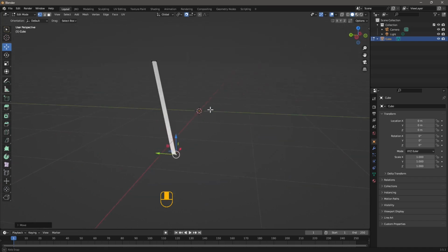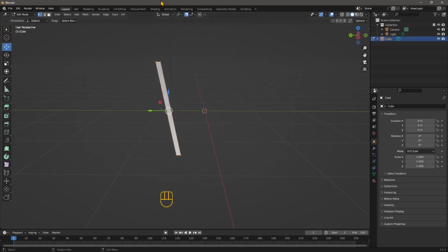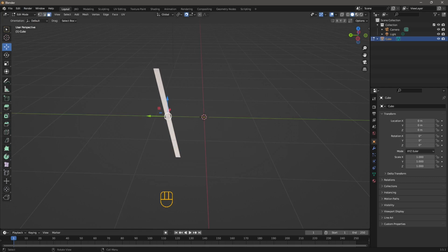So how can we do this? We can select all the faces, all the vertices, or all the edges. It's fine. It's the same exact thing. So let's select the face. And since this is a face, it's going to create a solid right away. If you have an open curve or a segment, it's going to create an open poly surface.